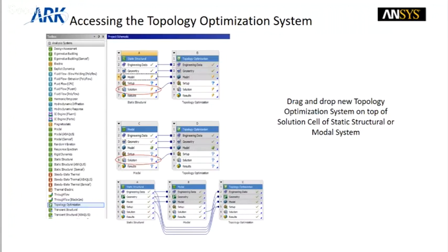That parameter may be geometry, it may be your boundary conditions, it may be your mesh quality. If you are going for small scale applications of optimization, I recommend you go for topology optimization. If your structure is huge, with assemblies of different parts, then it is best to go with design explorer, which will give you optimum results for the best suited values.